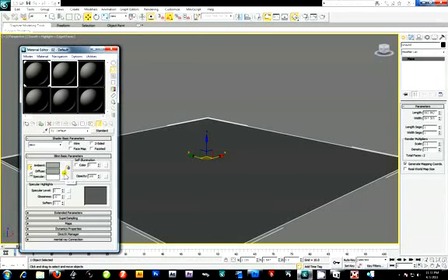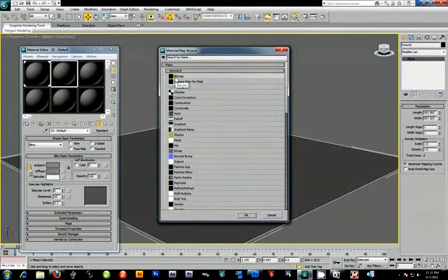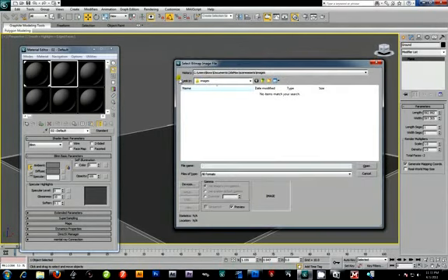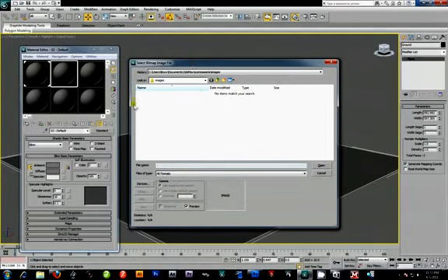I'm going to go ahead and find my first texture, which is supposed to be a ground, so I'm going to use a concrete type of texture, at least for this scene. Right here in the none slot, I'm going to open that up. Notice our material map browser opens, and then I'm going to hit bitmap. That's the universal button. It doesn't mean you're going to throw bitmaps in there. It's just letting you know you can open up and slide any image in there, from JPEGs to bitmaps, PSD files. But to be honest, you're going to want to use JPEGs.